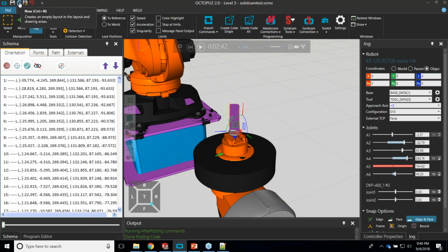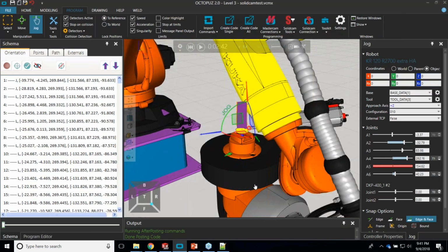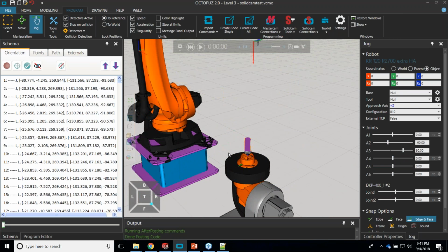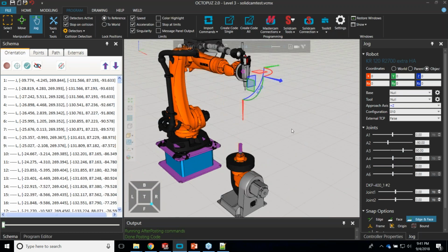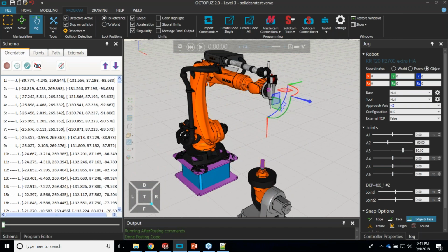And then one other question for you, Justin, too, is if you had a dual head robot, are you able to program both robots all within the one program, or do you have to create separate programs and kind of copy and paste them together? It depends on the brand. I know that our engineering team, if I ask them that question, and I have, their response would be, show me an example of some code, and then it would be a case-by-case basis, because it really depends on how it's currently being structured. And some brands structure it very differently. And some brands have different ways, like I know Fanuc, there's a couple of different ways it will appear.